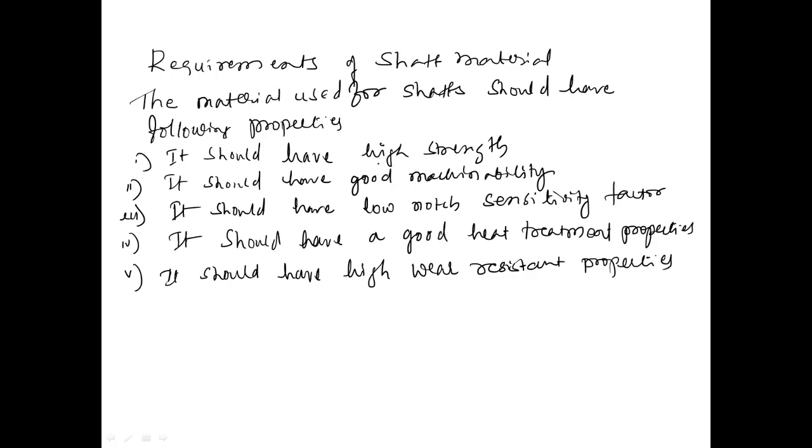So first thing is it should have a high strength. Because if the material is of very high strength, you can go for a smaller dimension shaft to carry the large power. Second one, it should have good machinability, because based on the dimensions, to decrease the size of the material to the required diameter, it should give good machinability.